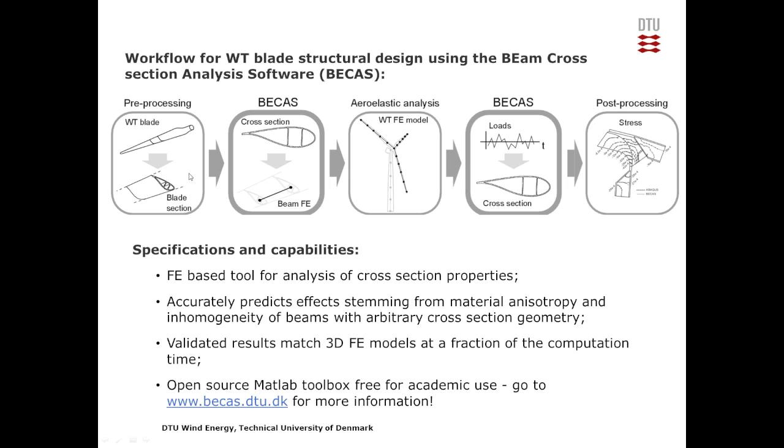So this is the first use of Becas, as you can see, as a pre-processing step before entering the aeroelastic analysis tool. Then you can also use it again as a stress recovery second analysis, where based on the loads that you calculate from the aeroelastic analysis, you can go back to the cross-section finite element mesh and determine the stresses, or some recent work we've done includes also crack and fracture analysis.